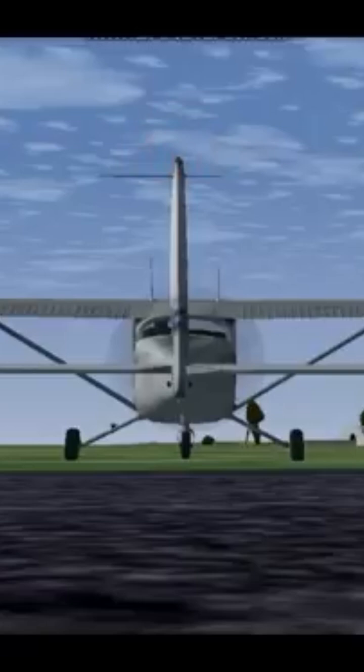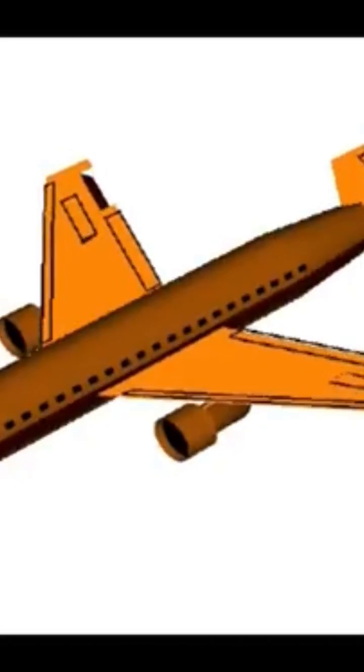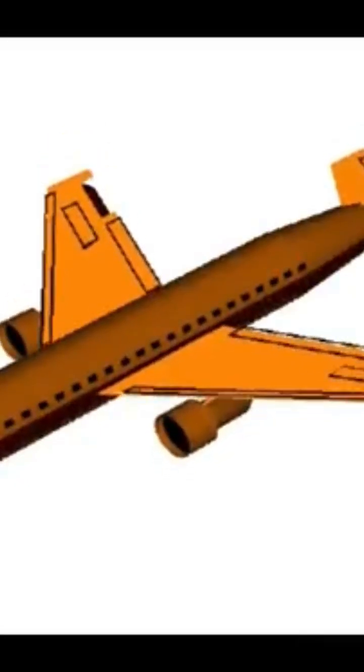This will create different lift forces in each wing. The one with the aileron down will have increased lift, and the one with the aileron up will have reduced lift. Now we have up and down acting forces away from the center of gravity. The net effect? The aircraft will roll. That is to say, it will rotate about its longitudinal axis.